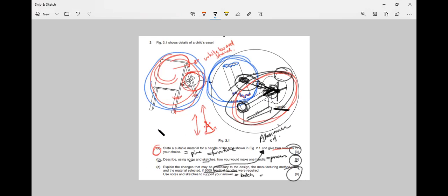You don't have to have 100 sketches. Just make sure that next to those 2 really good sketches, you do tiny little sketches where you zoom in, show a hidden detail, and you do it quick. Remember the way we practiced doing quick sketches when I timed you? That's what I want you to do here. Don't forget that. That is something useful that you can always apply.